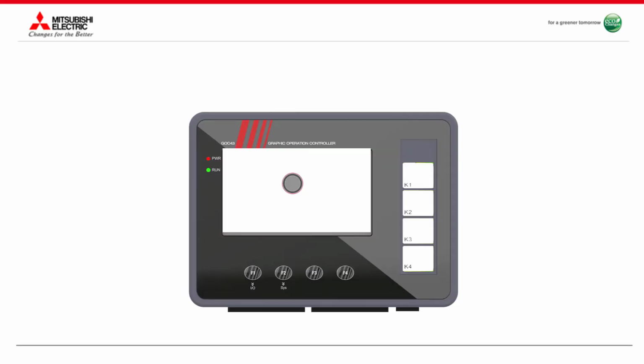The device shows the user screen. You should be able to see the lamp showing the status on the device screen. Now we will test the application. Press the K1 key and confirm that the red LED on the key turns on. Also the lamp on screen is now showing red color. Releasing the key will turn off the LED and also the lamp on screen will change back to normal state.